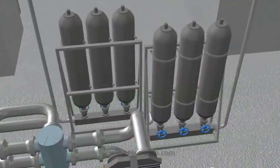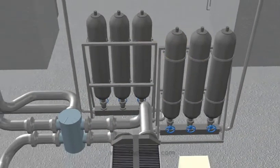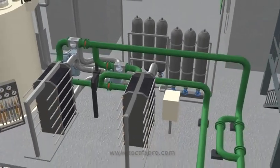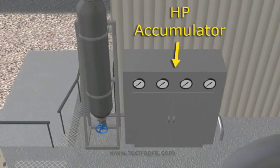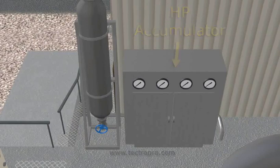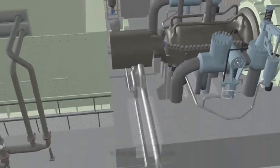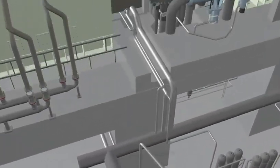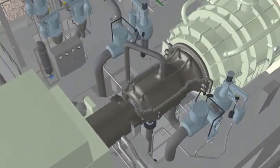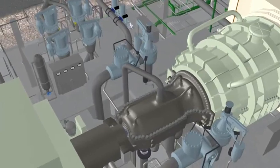The lube oil accumulators help dampen any pressure surges in the oil supply to the journal bearings and thrust bearing in the turbine generator package. The high-pressure accumulator dampens any pressure surges of the oil going to the main stop valves or governing valve servos. High-pressure oil comes from the high-pressure sections of the main and auxiliary lube oil pumps and is used to control all control and stop valves on the 3 steam systems.